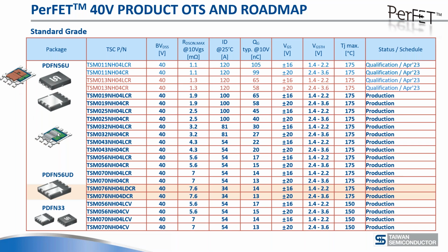The disadvantage is that the metallization scheme for making this product is more complex than this one, so you actually lose some wafer cost. Everybody makes their own trade-off on when to introduce the copper clip package or not, and we have chosen to do it for the big die only.